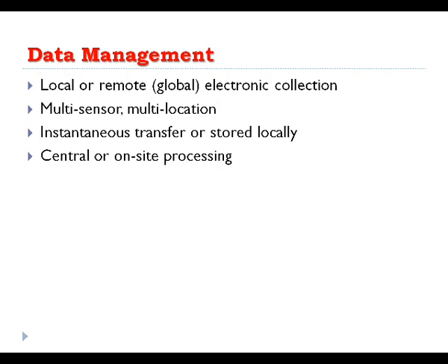GreenSeeker, for example, is collecting information about the chlorophyll status of a corn plant, processes that information, runs it through some algorithms and models, and generates the fertilizer nitrogen recommendation so that we can apply it on the boom on the back end of the machine. All this happening instantaneously. And we're using multi-video. Not only the data, but photos and video and sound are all part of the system that we might be employing in the future to work with this.